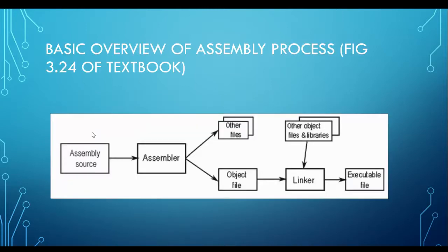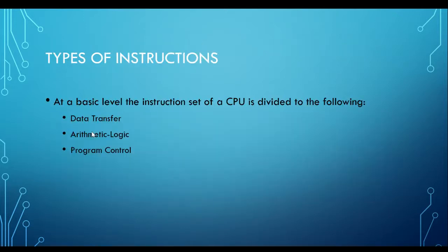So this is the whole process, from the notepad. You write your text file in your notepad until you get something that you can burn inside your memory. These are the things that your IAR has actually taken care of for you. In your assembly language lab, you will have libraries. The linker tries to extract whatever libraries you included inside the file and convert it into an executable file.